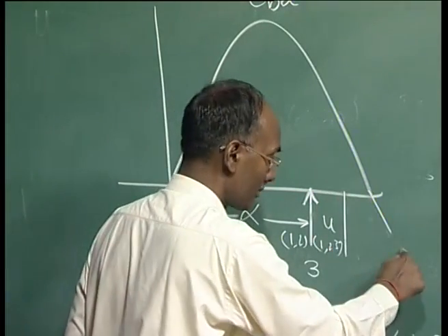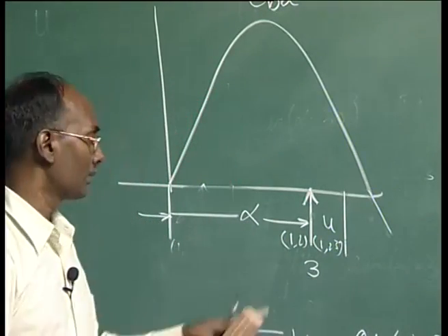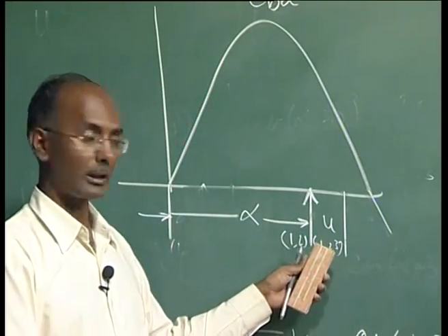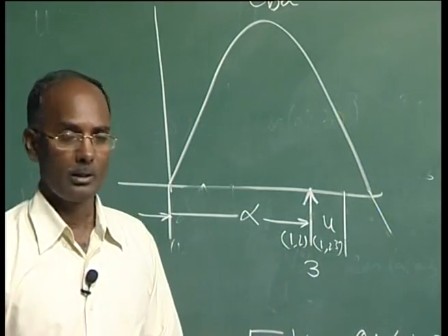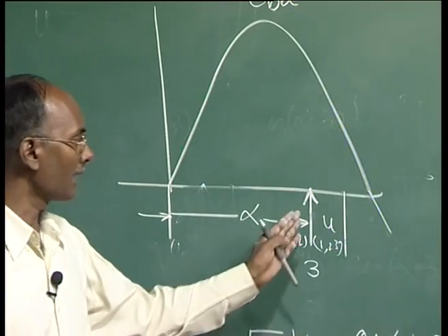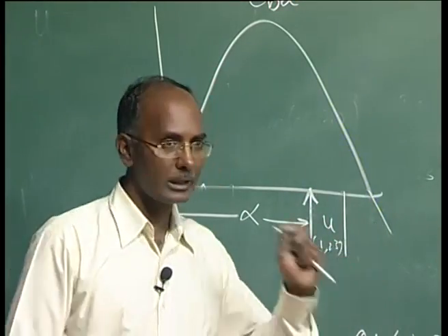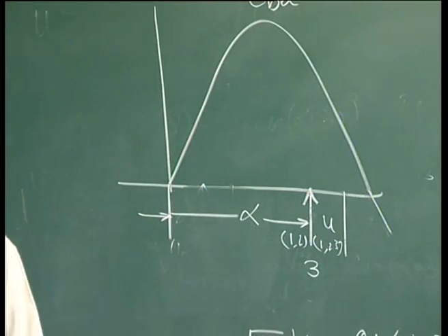The possibility is that the voltage goes negative and this valve 1 is picked up again; valve 1 can continue conducting and valve 3 can go off again, meaning it will take the current and then again it will be 0, and that will be commutation failure. So, in this period of inverter operation we have various possibilities.